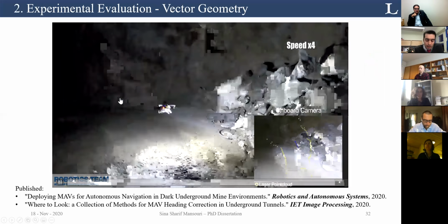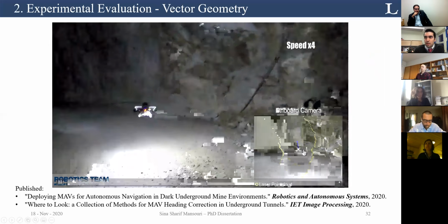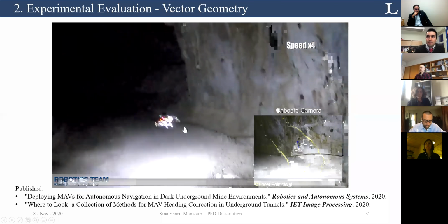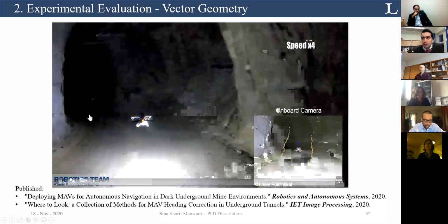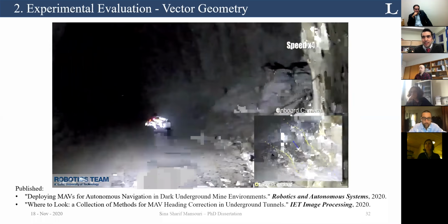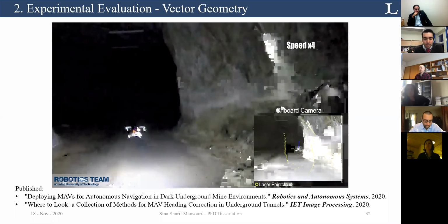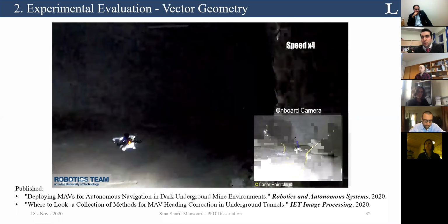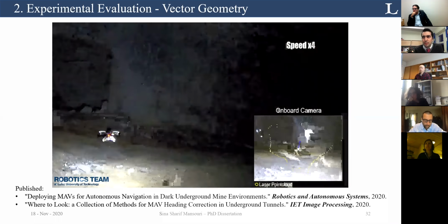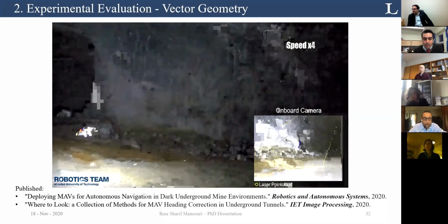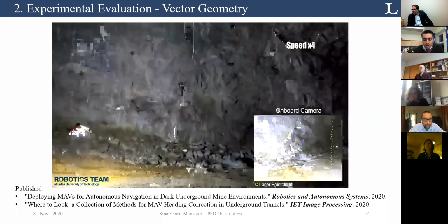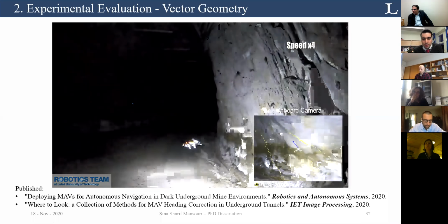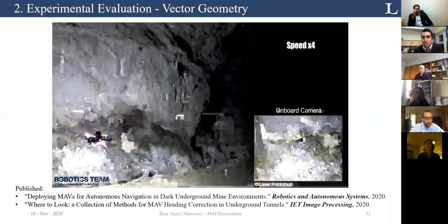In this video, mainly the blue arrow should be observed. The problem that I see here is that we had these S movements. One reason is the low reliable range of the 2D LiDAR that we had at that moment, which was I think 4 meters. Another one is that I noticed that relying on only three beams is not robust enough, because sometimes you have wet surfaces and you think it's open, but it's actually not an open area.